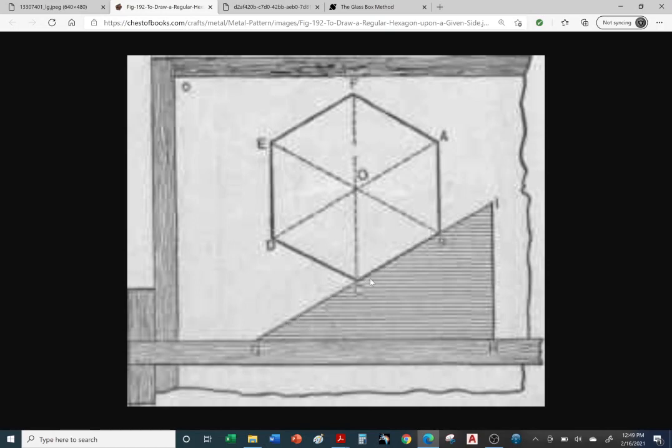So this is at a 30 degree angle. Then you would flip the triangle to draw this line. Okay, let's go back to this line. So you line up your T-square with the edge of the table. Line up your triangle with the T-square. Draw your line. And then you can slide it up to draw this line.